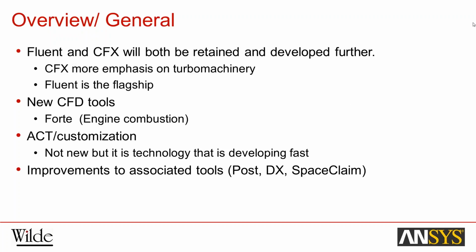Good morning. We'll just start off with a quick overview of what we're going to be talking about. We're going to discuss a few points to do with FLUENT and CFX, and we're going to cover some of the extra tools in Workbench which have an impact on CFD modeling. We'll start off by saying that FLUENT and CFX will both be retained in the future and continue to be developed as far into the future as we can know about, CFX perhaps with more emphasis on turbomachinery, with FLUENT as the flagship. There are also new CFD tools coming in. Forte for engine combustion is coming to the ANSYS stable, but we will not be covering that today.